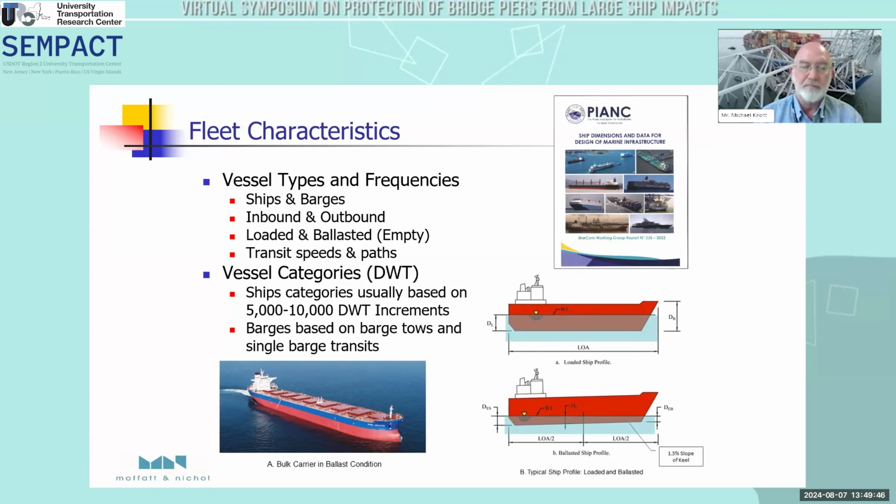The lower left shows a bulk carrier that's empty, and I've even seen ship bows where the bow is sticking up out of the water. So it's very important to include the ballasted or empty condition when doing your risk analysis. And so your ship might be 45 feet deep loaded and you have a pier in 30 feet of water, and maybe that vessel runs aground. But in the ballasted condition, that vessel might only have 9 feet of water at the bow. It's 1,000 feet long. It can potentially strike your pier, and you should be considering that.